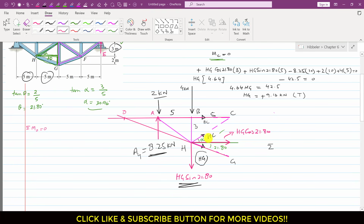Since if we apply the summation of moment about that point O, then this HC is going to produce the moment about that point O, and we will need to resolve this HC force into its components, right? This HC force will have two components. It will have one component like this, and one component which will be acting in this direction, that is in the upward direction. This is the cos component of HC, this is HC cos of alpha, and alpha is 30.96, and this one is the sine component of HC.